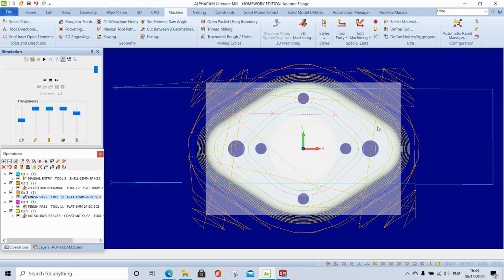Okay, so a few things to do before you get to the point of extracting the holes and doing the normal 2D machining, which we would have done. This 3rd and 4th op are normal 2D machining. You just have to extract your geometries to be able to do that, and remember to pick your tool direction as well, otherwise it'll machine into the block.